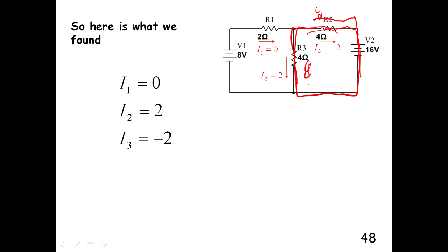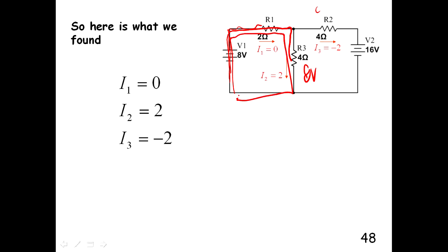So each one of these resistors has a voltage drop of 8 volts, which means this one right here has 8 volts, and since we're putting a battery on here, his loop also has to work with Kirchhoff's loop rule. Since we already know this is 8 volts right here, there's no current that's going to flow through here, because if we go up 8, down 0, down 8, we're back to 0. See? So Kirchhoff's loop rule works there. It was a lot of fun. I hope you've enjoyed this trip down Kirchhoff's loop and node rule lane.